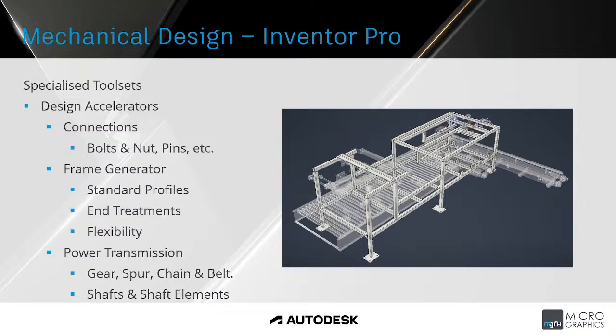Here we have some welded steel framework for a conveyor belt. And we have what's called Frame Generator inside of Inventor that allows users to create reference geometry. It could be as simple as a box with a couple of sketches on it, and that represents where your frames would go. Then Frame Generator allows you to choose standard profiles, place those frames down on the reference geometry, and generate the final frame.